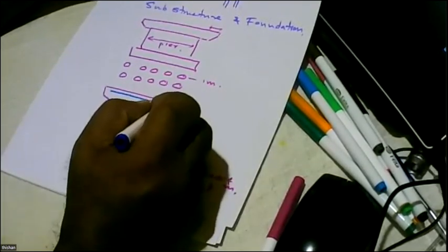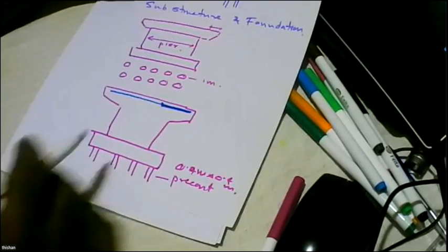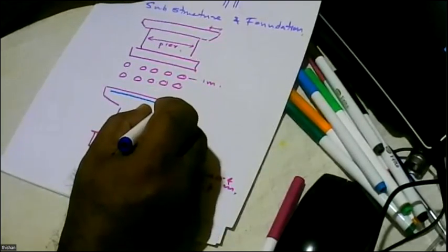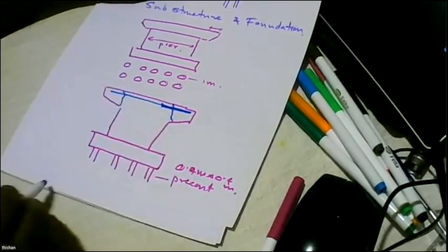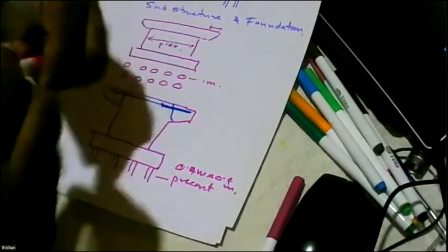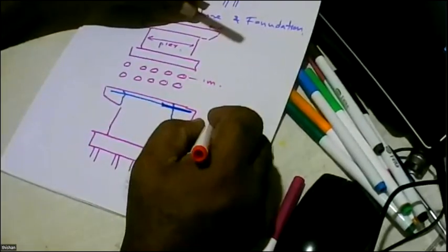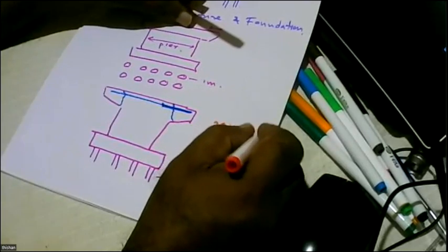If you look at Eurocodes and all the codes, generally we are discouraged from curtailing a lot of bars at one section because there can be stress concentrations. So what happened was there were cracks like that. And this was at the latter part of the project, somewhere around 2010, 11.